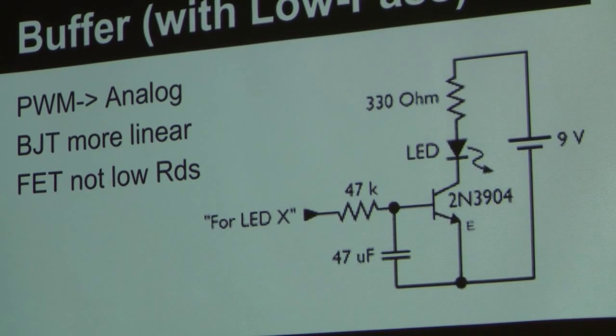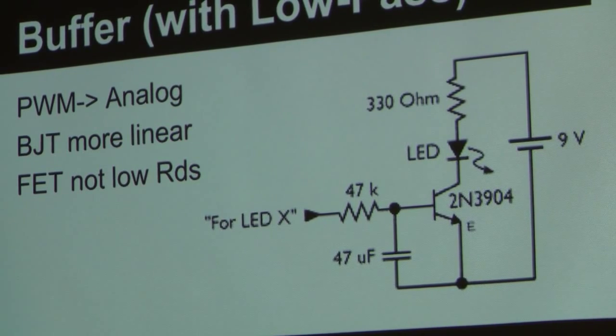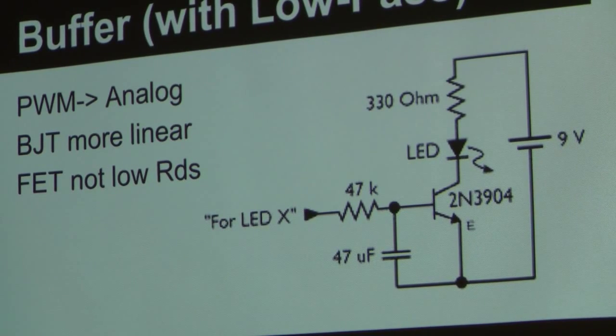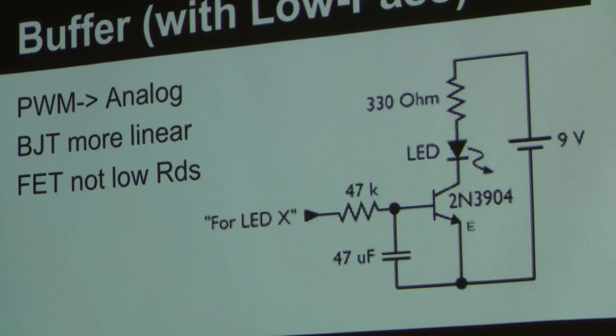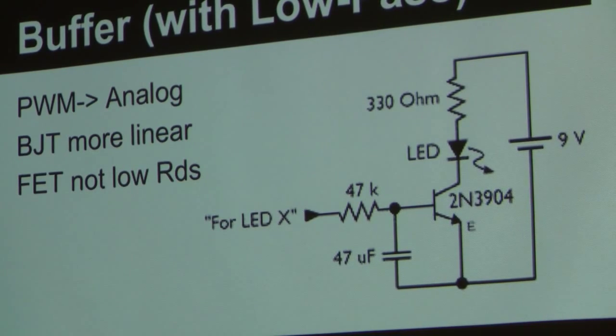No, not really. On a BJT, as long as you're not exceeding your pull down, it immediately clamps down to 100 volts or 200 volts across the VCE, across the collector and emitter here. But if you're running it in an open mode, you can do linear control, where you can say, I'm going to put 5 milliamps through. Depends on where you are in the curve, right? If you're staying on this side of the saturation curve, then if you put in 3 milliamps versus 6 milliamps, you get twice as much current from a BJT. But you can't say for a MOSFET, oh, I'm going to go from 2 volts to 4 volts, and I'm going to get double the current. I can guarantee you're not going to get double the current.